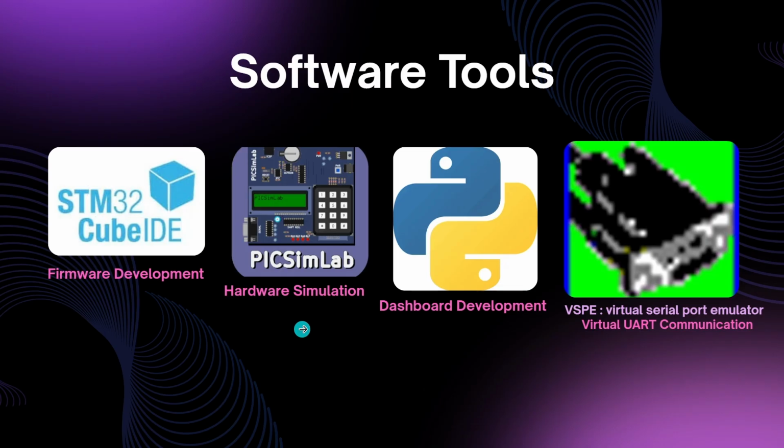Next, we are using Python to develop the real-time monitoring dashboard. We have used a library like matplotlib, where the data is received and displayed graphically. Next, for sending the data from the STM32 to the Python dashboard, we are using VSPE, which is a virtual serial port emulator. This basically transfers the data from the STM32 board to the Python dashboard through the UART protocol.